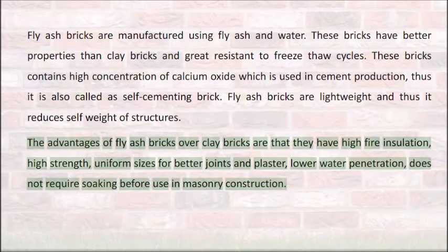The advantages of fly ash bricks over clay bricks are that they have high fire insulation, high strength, uniform sizes for better joints and plaster, lower water penetration, and do not require soaking before use in masonry construction.